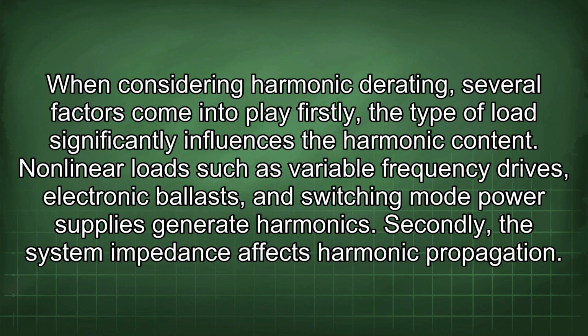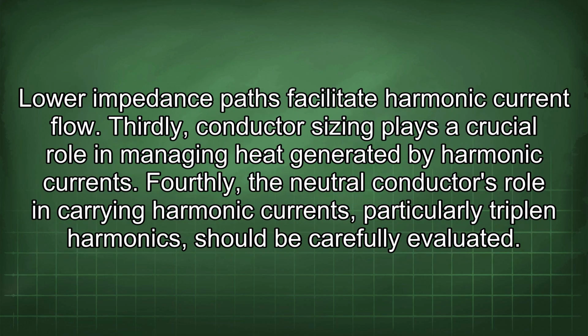When considering harmonic derating, several factors come into play. Firstly, the type of load significantly influences the harmonic content. Nonlinear loads such as variable frequency drives, electronic ballasts, and switching mode power supplies generate harmonics. Secondly, the system impedance affects harmonic propagation. Lower impedance paths facilitate harmonic current flow.